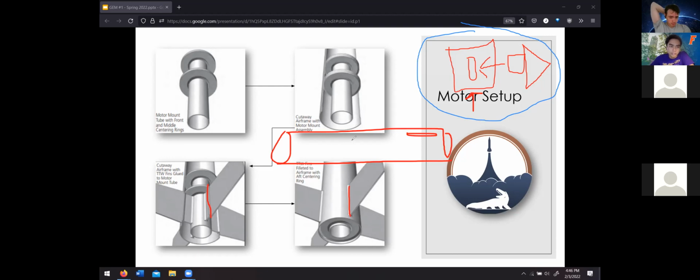So then what you're doing is you're cutting the fin so that it goes through the wall of the airframe as far down as it can, up until the motor. And then from there, like you said, there are these little sections where you would just epoxy it. So your fin now has 3 points of contact where it is epoxied to the airframe, making it probably as secure as it can possibly be. That's just a really not in depth look at these manufacturing methods.